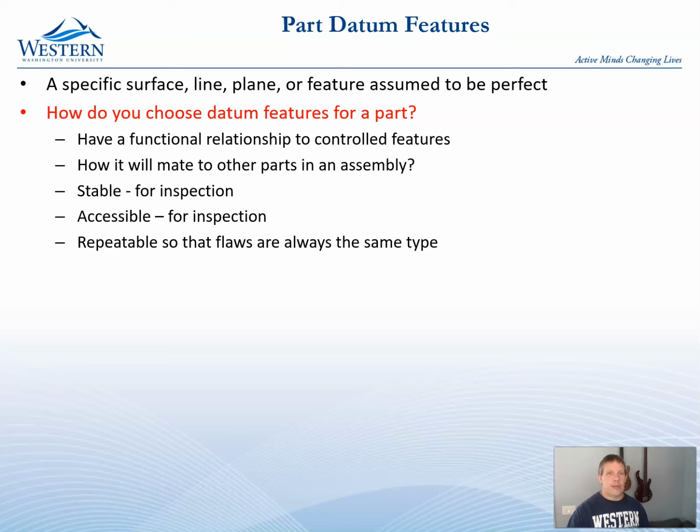And one of the things that we're going to talk about in this class is, okay, you called that out as wanting to have GD&T with respect to this feature. What is that going to cost you in terms of measurement time? Because the way that you go and determine that feature will require 1 or 3 or 9 or 27 measurements, and each one of those costs you money because they take time.